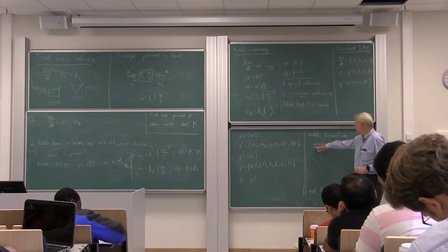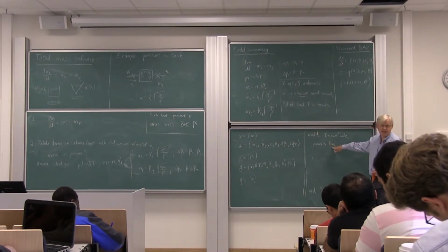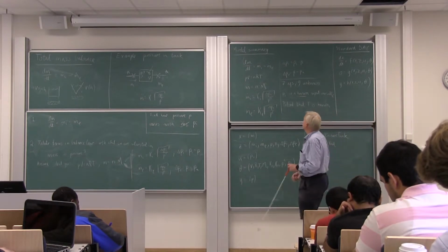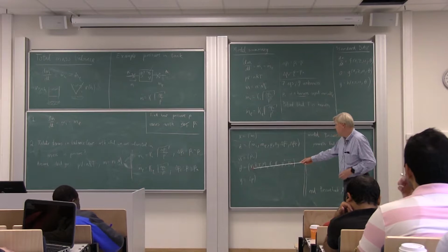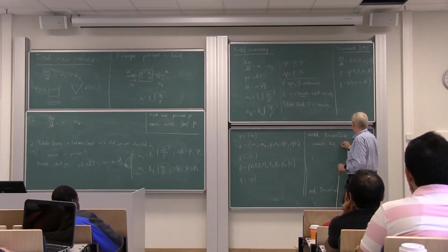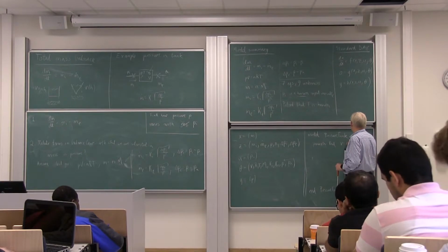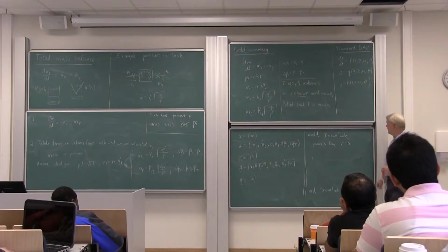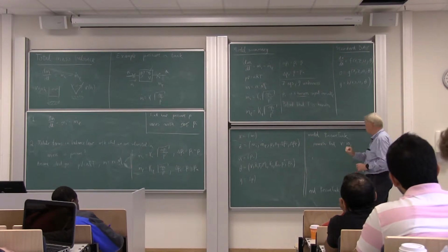So parameter says it's a constant, real says it's a real parameter, and then we just take the values we have here, v, let's say 10, and then every line has to end with a semicolon.